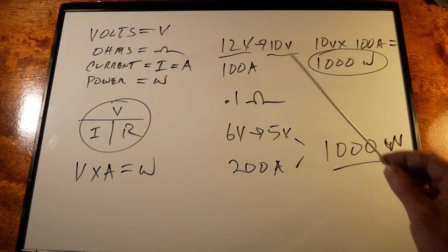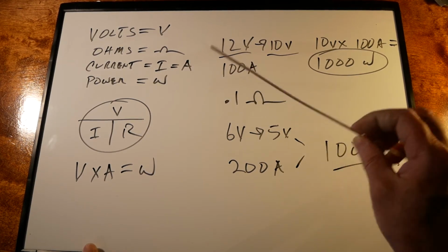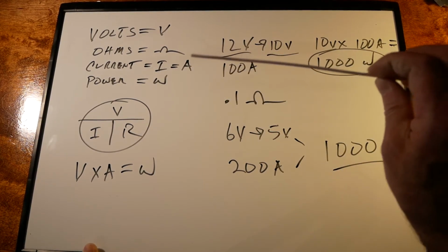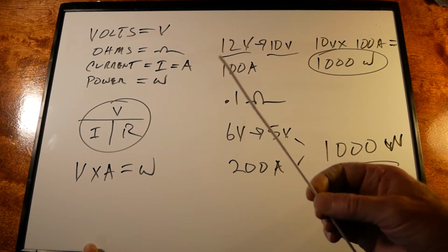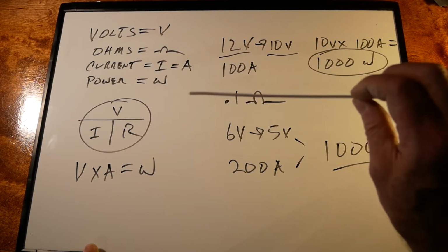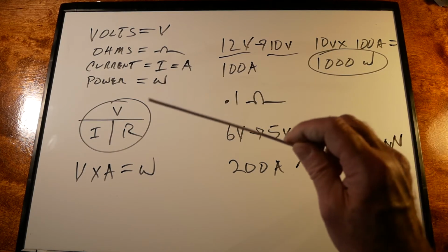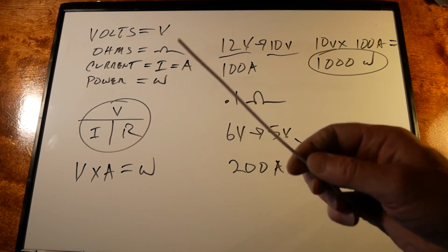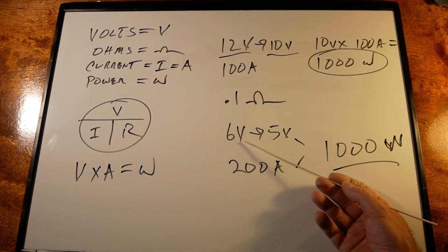For instance, this is a typical 14 gauge house wire. That 14 gauge house wire would move enough watts to start an engine at 120 volts line current. So we can get the same amount of power out of this 14 gauge wire at 120 volts as our 6 volt system can get out of a cable that's over 4/10 of an inch in diameter.